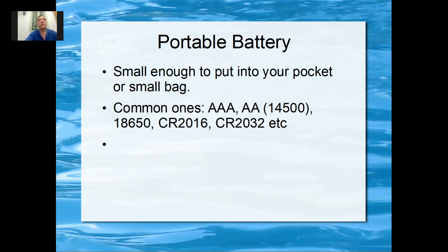Those are 3.7 volt. And then you have others like the coin battery, CR2016. This one means 20 mm diameter, then 1.6 mm thick. So this looks like a coin.